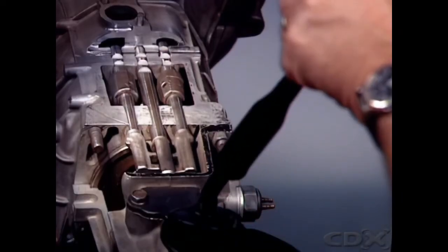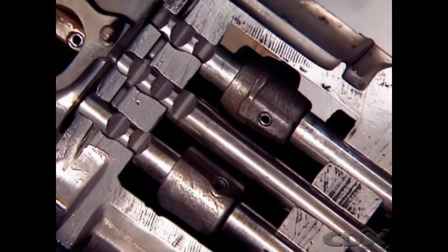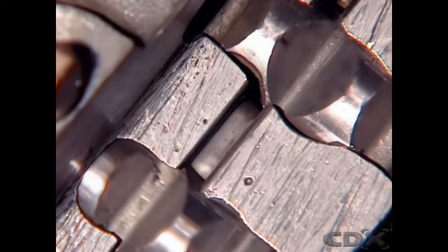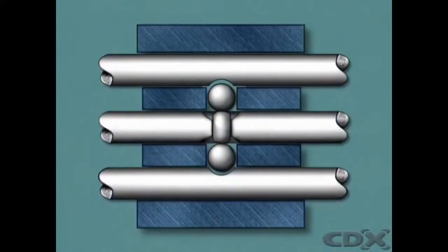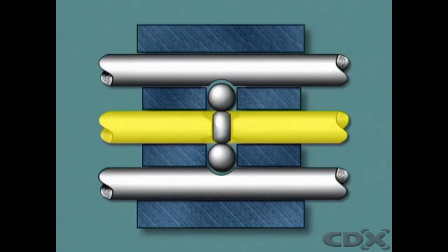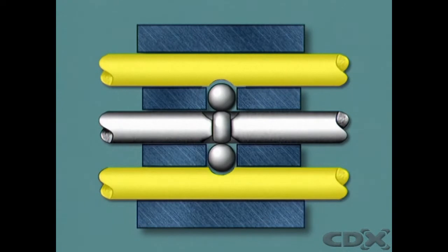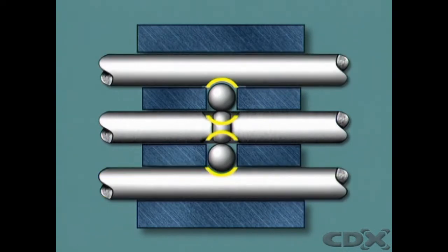When a gear is changed or selected, an interlock mechanism prevents more than one gear being engaged at the same time. In this design, 2 steel balls locate in the casing between the center and the outside shift rails, and in alignment with grooves machined in the shift rails. A small plunger is captive in a hole drilled in the center rail.